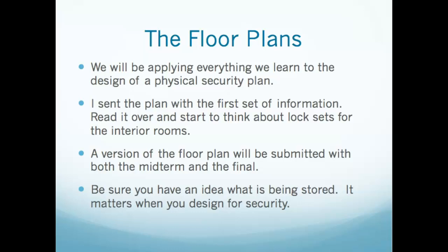Look, you've got an office, you got 2 offices, you've got a break room, you've got a conference room, you've got a file storage room, and I sent some information about the file storage room, and you have a big warehouse area. Think about the door locks on those interior doors. What type of lock set would you put in there, right? We went over the different types. Does it require a classroom, a storage room, a classroom security, a passage set, a privacy set, an office set? What does it require? And then think about why. And if you want to get ahead a little bit, you can go ahead and do that, and then write up just 1 sentence as to why you chose that. And just keep that handy, because we'll have those to plug into the beginnings of our security scope document. Okay?